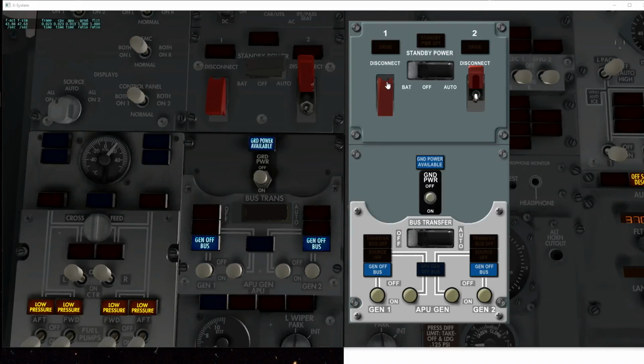I can't remember which way it goes, but anyway, this provides a way. See, the engine can run at any variable frequency, so you can't just hook a generator up or you'd have variable frequency. So you need some way to get a constant speed to make sure the generator is producing power in a constant way.